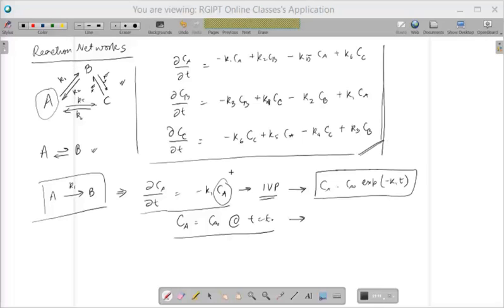When you implement computing techniques, you start with the initial known value at t equal to t0, and then find out CA at delta t a little later, and use this information and previous information to find CA at 2 delta t. If you know the CA value at t equal to 0, and dCA/dt at this point is known, you use this equation to calculate CA at the next step.